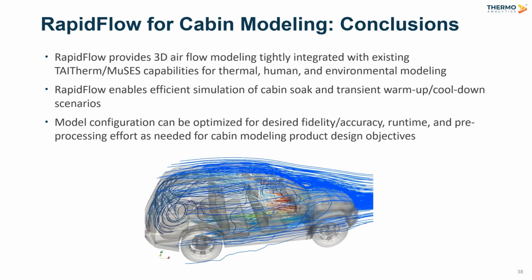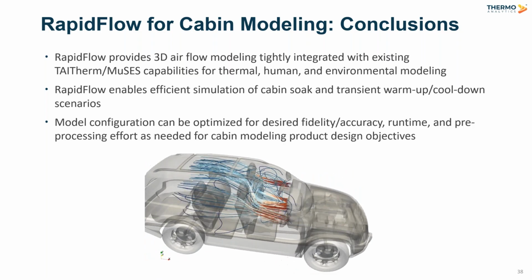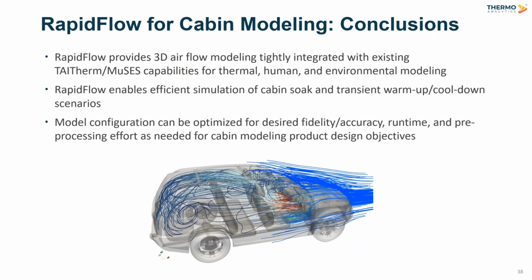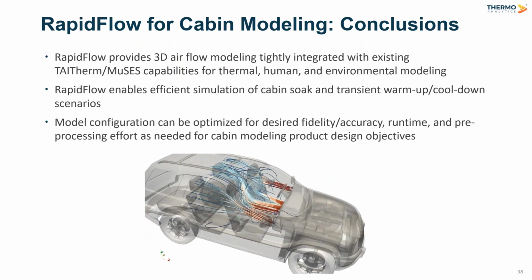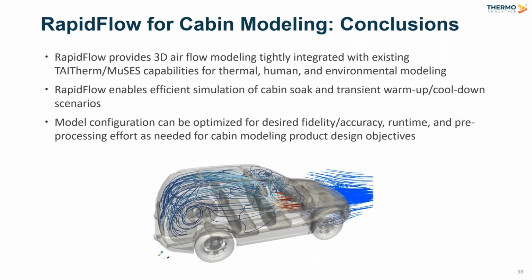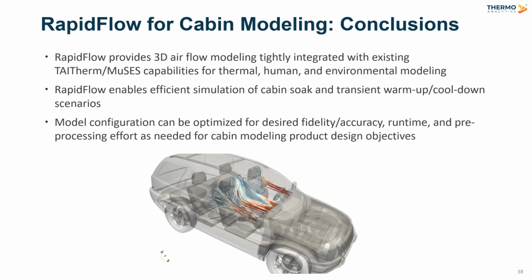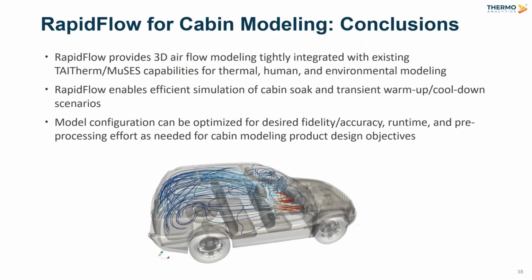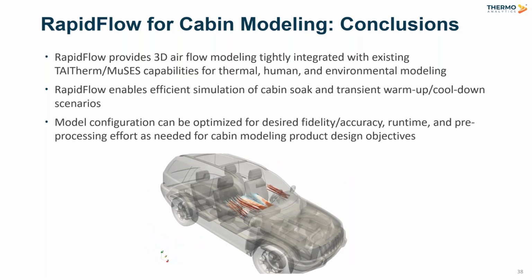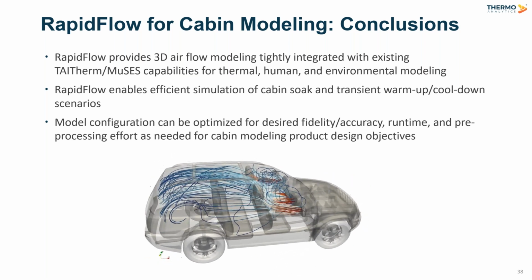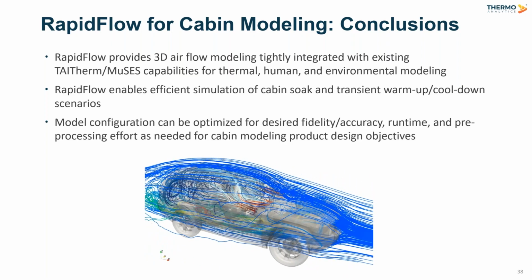How is the flow split between recirc and fresh out in the cabin handled, the flow outlets in the system? Good question. In this example, it was 100% recirc and just a single outlet, so that's kind of the simple case. If you did want to split that, you can either have outlet boundary conditions, which are essentially fixed pressure, or you can have an inlet that has flow specified out of the domain, which is a common technique used in a lot of CFD tools as well.